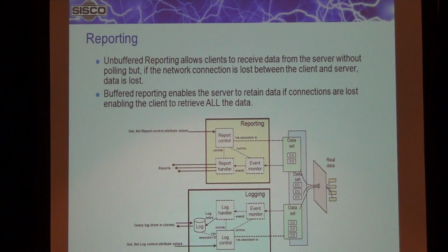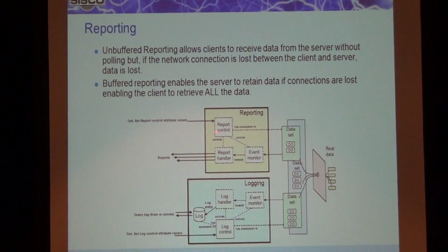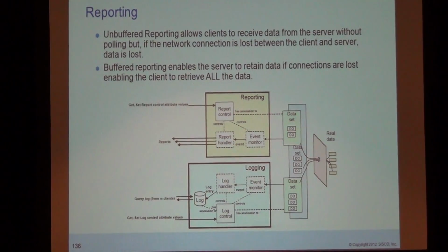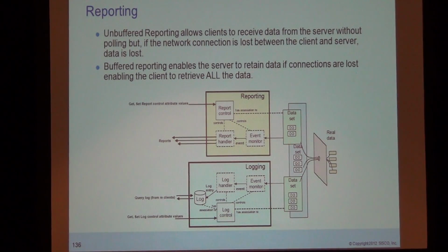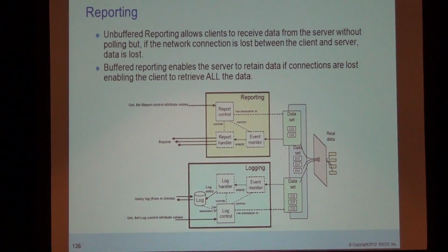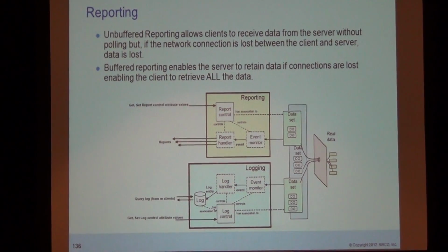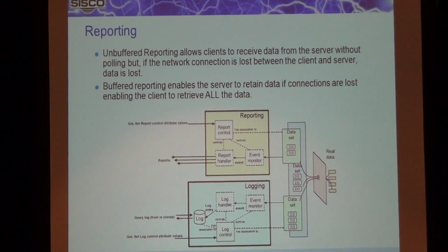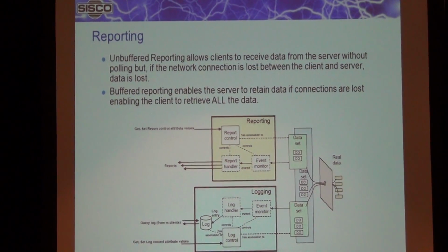Reporting is really a very nice model that allows the client to interact with the device through a report control block to tell the server how you want data to be reported to you. So you can have control over the integrity period and the buffer times, in other words, how fast reports will be sent to you. Do you want data change reports or just quality change? Do you want to include the names of all the objects in the report, or just send me the data values? All of this information and control over the reports can be done by the client interacting with a report control block.